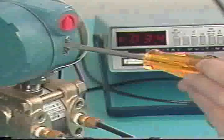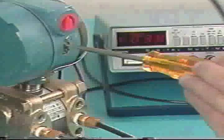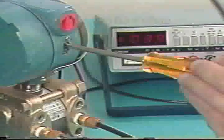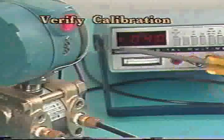Once you've made a 5-point check based on the total span, you'll identify whether the transmitter needs calibration and correct any errors present. After the transmitter is verified to be in calibration, you'll suppress or elevate the zero by the specified amount. It's good practice to recheck the transmitter calibration once the zero elevation or suppression has been made.